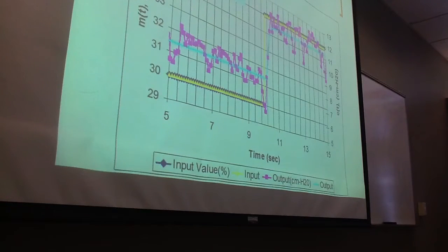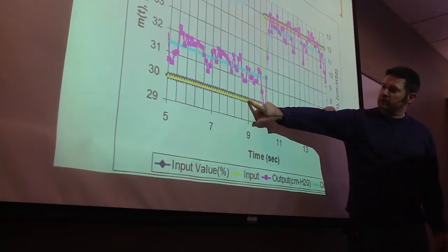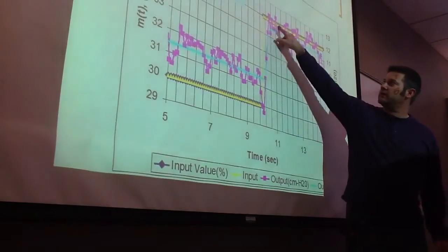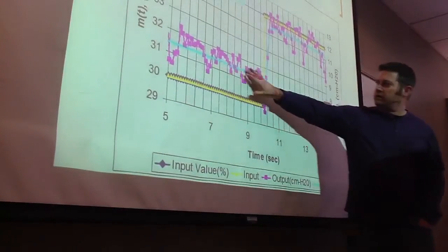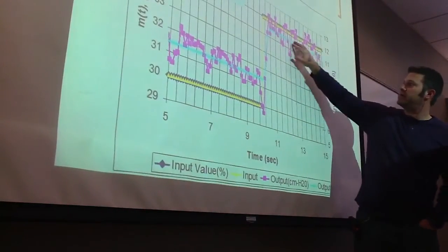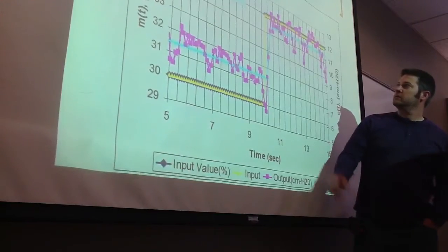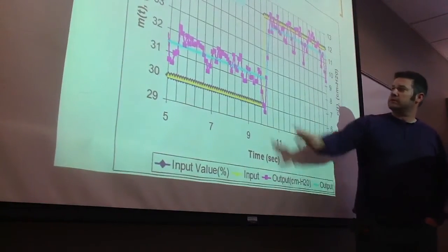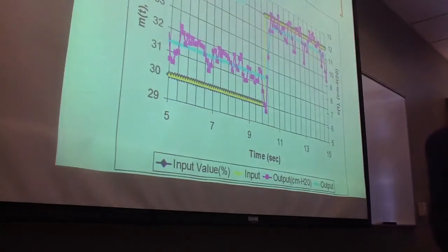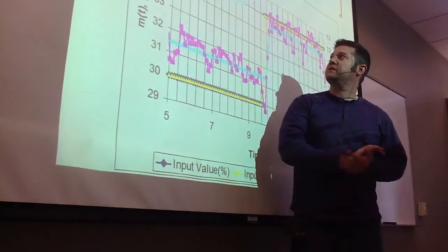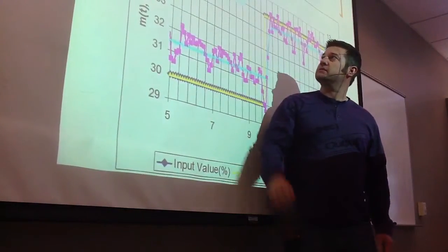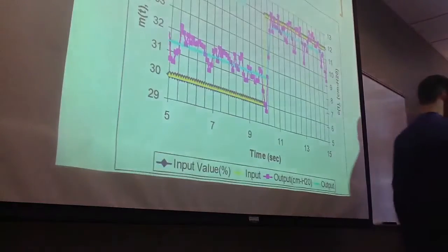This is the modeling of the step response. You can see our inputs lined up fairly well, as you would expect. Our curve here for our output lined up pretty decently. There's maybe a little corner here, but it was a pretty good fit. If you look up here, our gain came out to 0.7, our dead time was 0.2 seconds, and our tau was 0.1 second.